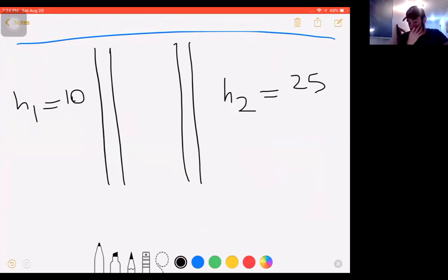I'm going to draw the actual resistance network of it. There are 5 layers basically. First layer from the inner space that is held at the room temperature, from this point all the way to the inner surface of the window, we have a convection term. Between the inner surface of the first layer and the outer surface of the glass layer, there is a conduction term.